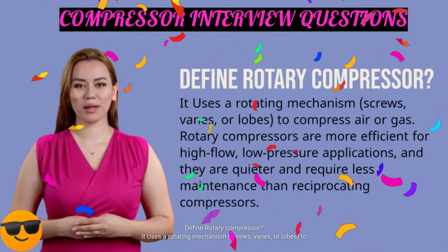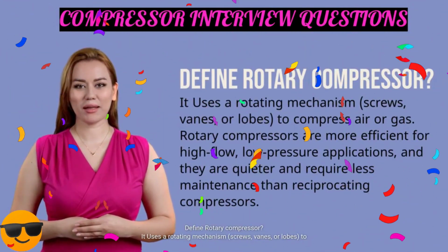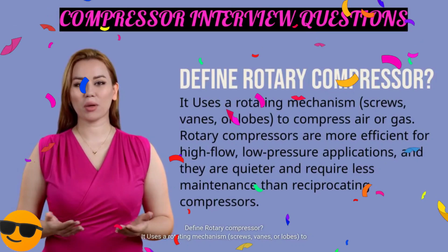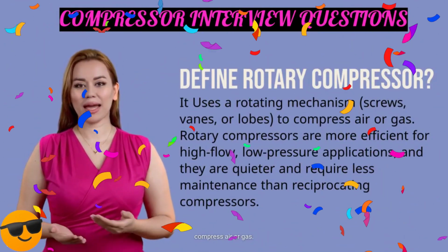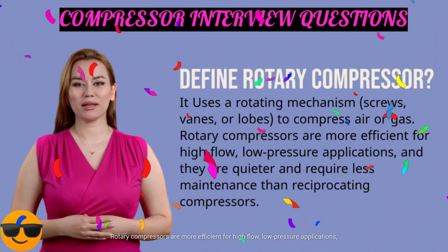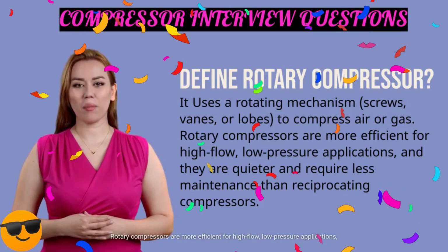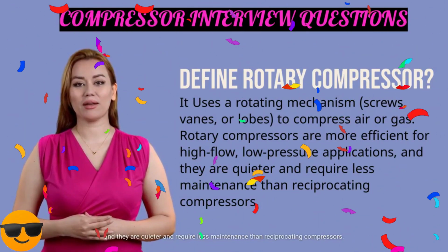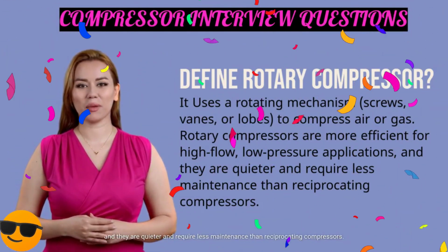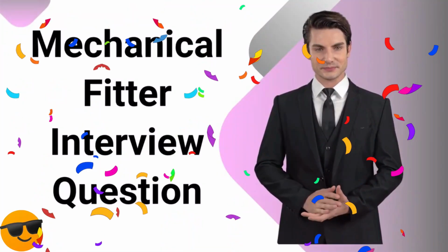Define rotary compressor. It uses a rotating mechanism, screws, vanes, or lobes, to compress air or gas. Rotary compressors are more efficient for high-flow, low-pressure applications, and they are quieter and require less maintenance than reciprocating compressors.